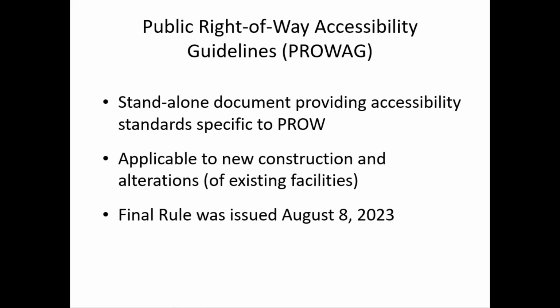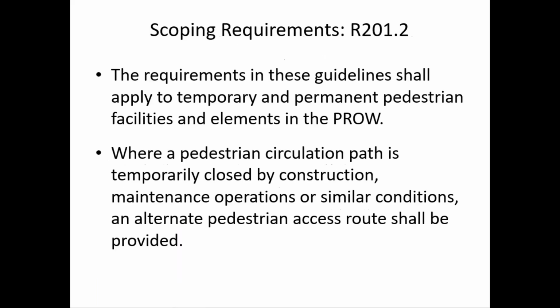But still remember, even though PROWAG is not enforceable yet, general ADA is enforceable. And remember that bottom line statement I mentioned a few times: public agencies need to make sure their facilities are readily accessible to and usable by individuals with disabilities. That still is enforceable. And the best way to show you're doing that is to follow PROWAG.